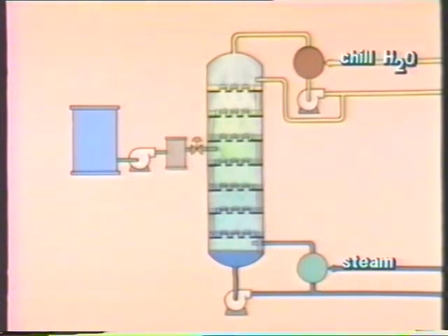Distillation towers have additional systems to help produce the best separation. Let's look at the top of the tower first. The process used to help control the overlap at the top of the tower is called refluxing. Refluxing involves reintroducing part of the condensed vapors coming off the top back into the top of the tower. Here's how it works.